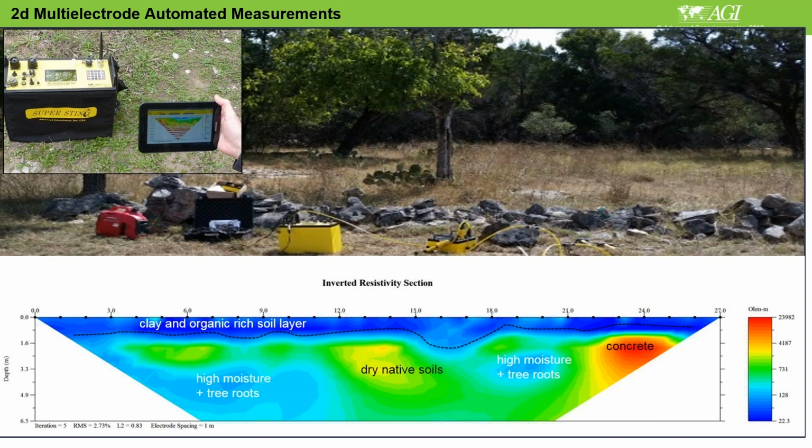Just consider not putting in more than 10% of your electrode spacing. What I mean is, if you have a 1 meter electrode spacing, try to put your electrode into the ground about 10 to 15 centimeters. That will make it a point source. With multi-electrode spacing like 1 meter, 2 meters, 3 meters, depending on that, you can put in a little bit more and more.